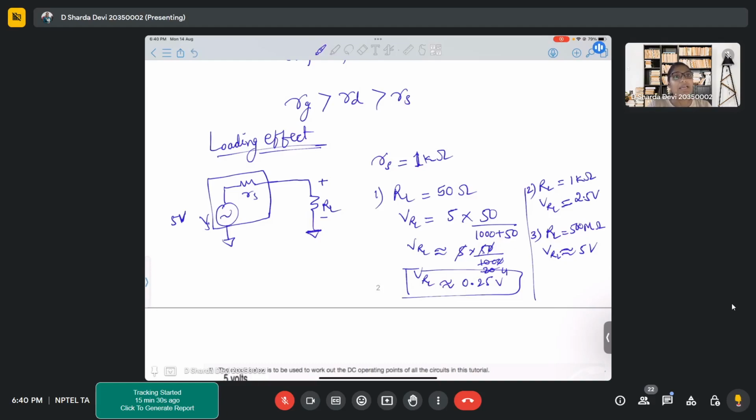That's why we also talk about gate, drain, source impedances, as well as, if there is a voltage source, the impedance of that voltage source, and if there is a current source, the impedance of that current source. All this is done for that particular reason. Even in terms of a diode, last time you might remember there was a piecewise linear model. There we drew a diode with cut-in voltage, also with the internal resistance, right? That is the resistance that appears across the diode. So every element, even a single piece of wire, has its resistance and its impedance.